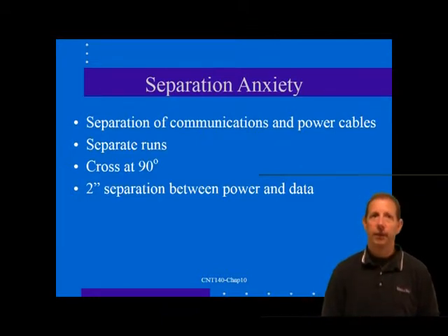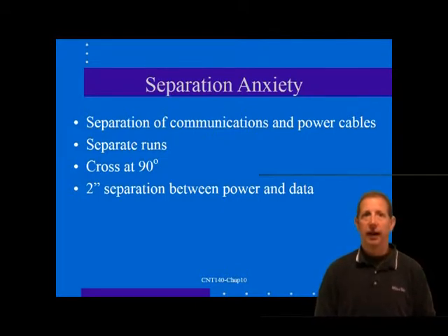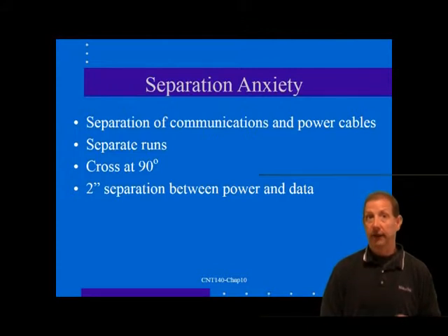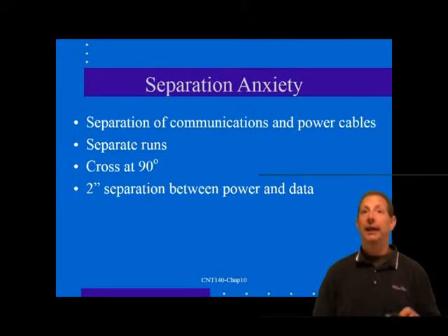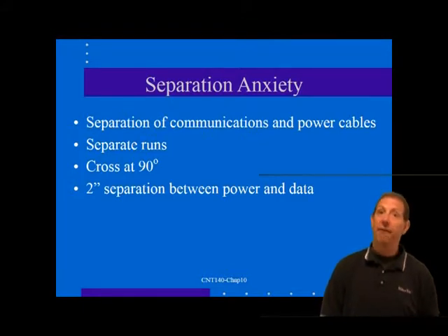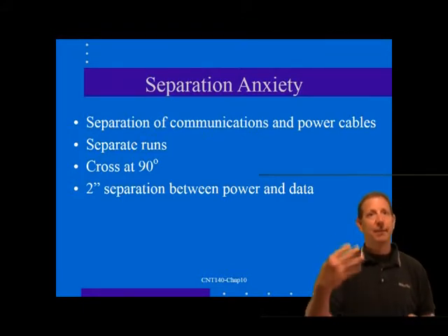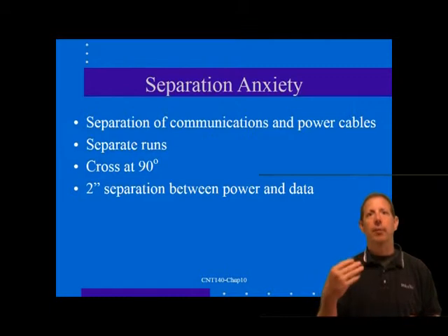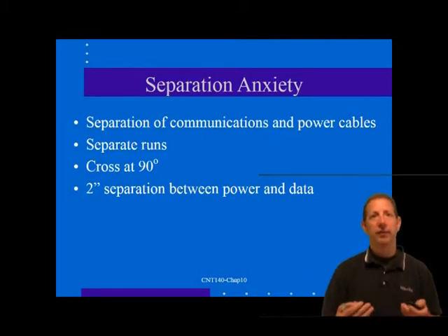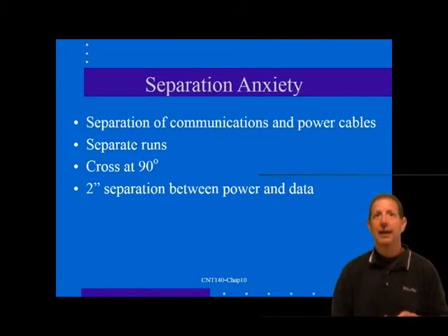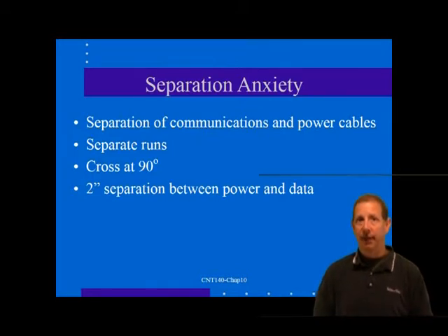Now, we routinely use LAN equipment that generates and is susceptible to interference to or from power lines. The closer we allow wires to be and the longer we allow them to run in proximity, the greater potential that we have for interference. Thus, the basic guideline here is to limit both the run length and the separation of these types of cables, even into a divided power communications cable tray.